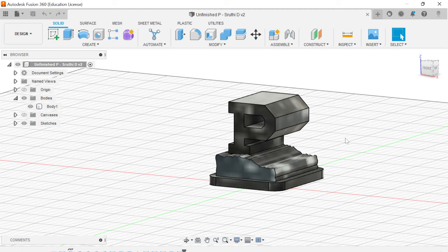Okay. So whenever you download Ultimaker Cura, you're going to get a big screen at the beginning. It's going to ask you what printer you're using. You can select any printer. All it's going to do is it's just going to change the settings just a little bit to optimize the whole process for that specific printer. We use a Creality one, but it's not important because we're going to be the ones printing it.